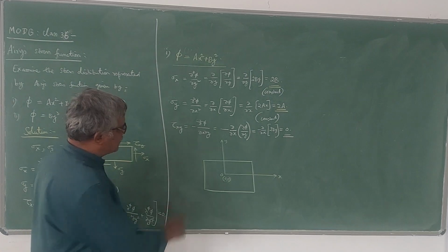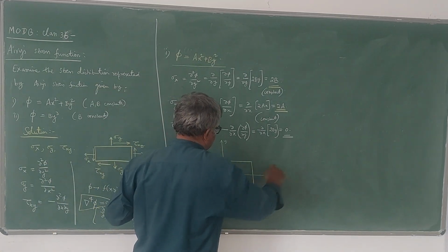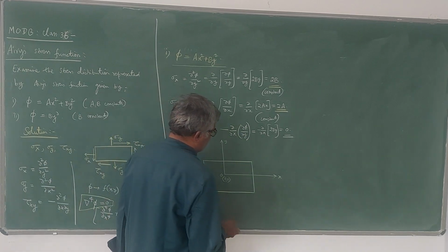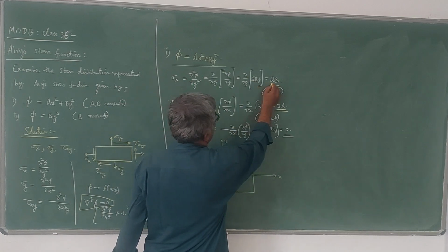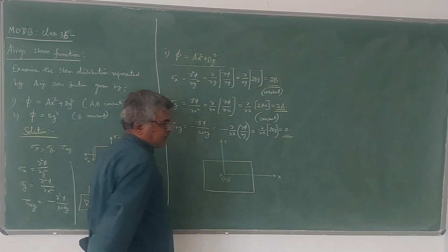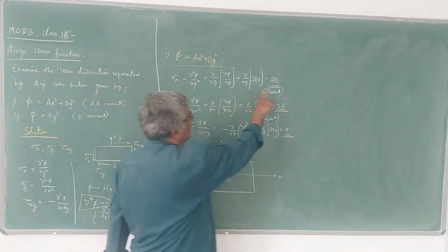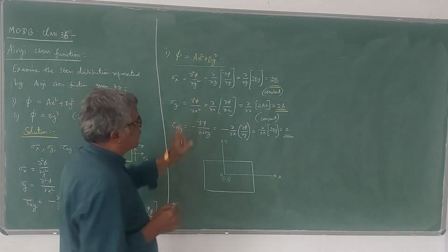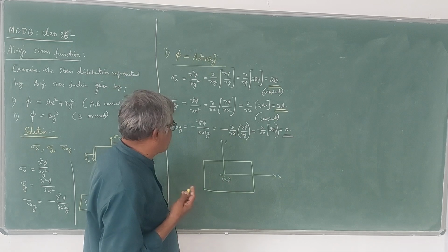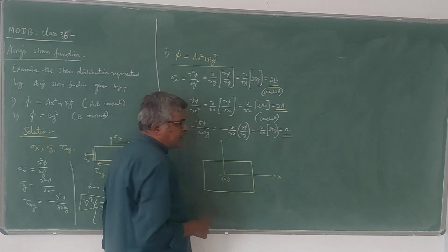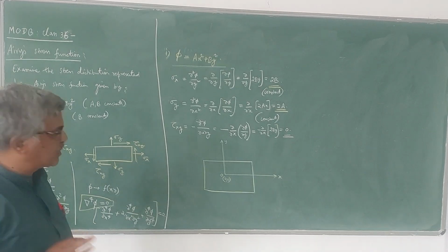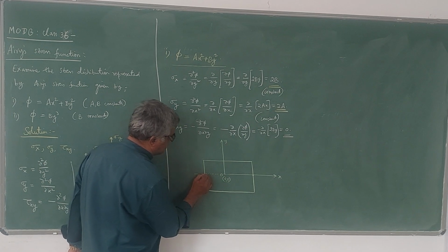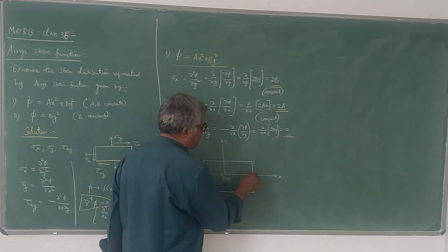So now here, this is the element. Sigma x is represented like this, sigma y is represented like this, tau xy is represented like this. Now how to choose this point is, you can see here, since sigma x is independent of x and y, it is constant. So 2b, let me take b as positive. Then sigma x becomes positive if you treat a and b as positive, unless otherwise given. So irrespective of x and y, the value of sigma x is constant. Here x may have some value, and you can extend this side. Here also you can have an x value.